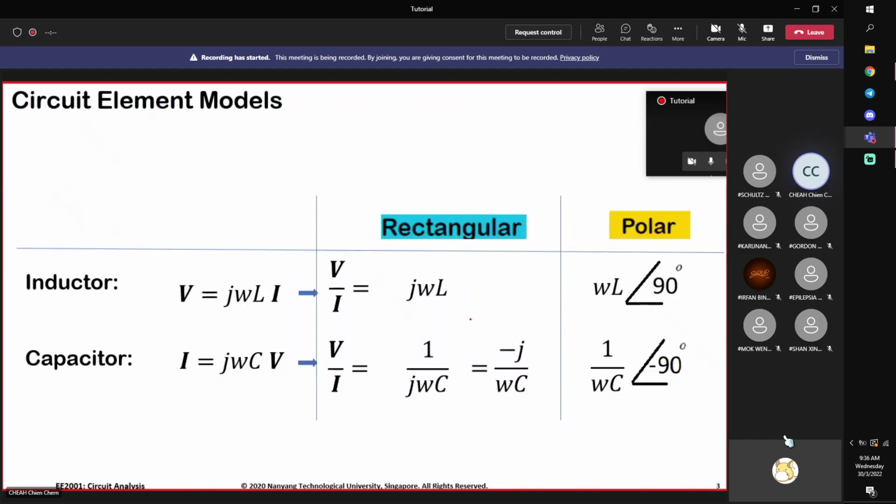Okay, we have also reviewed the reactance model in phasors. And this is related to our S domain analysis, because in S domain, inductance is SL, and capacitor is 1 over SC. This is called the impedance. In AC, we just substitute S equal to J omega, which means that we assume only steady state analysis, and only AC signals. This is 1 over SC.